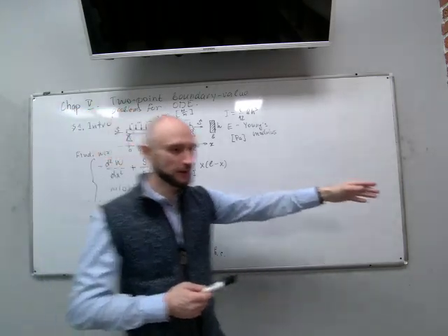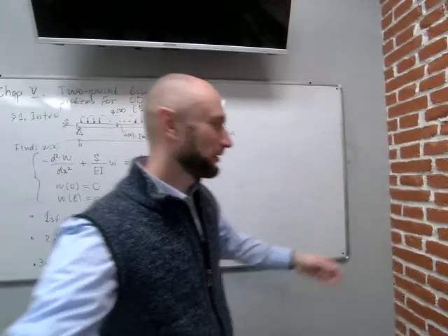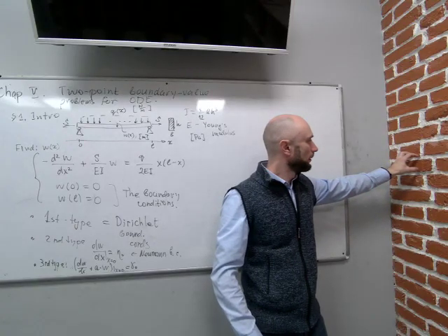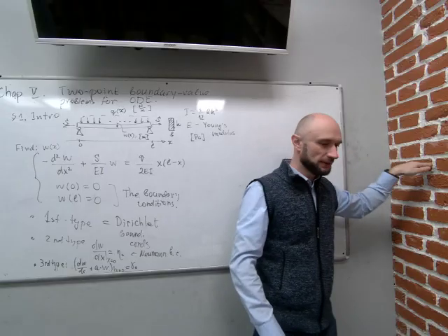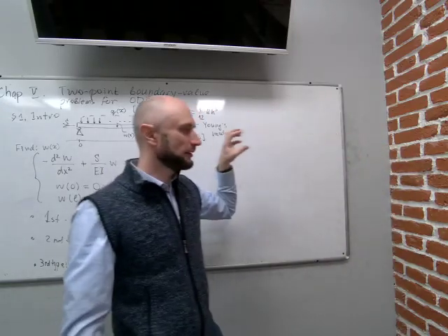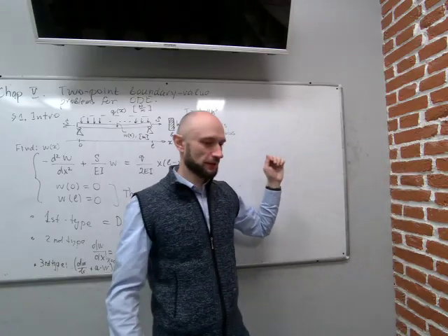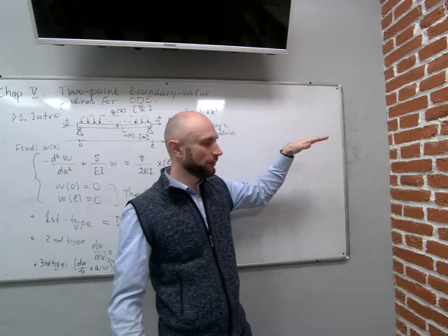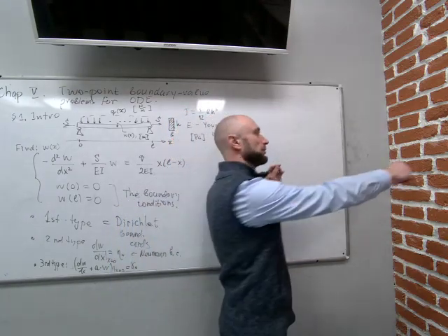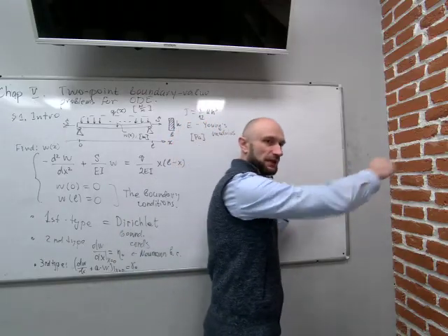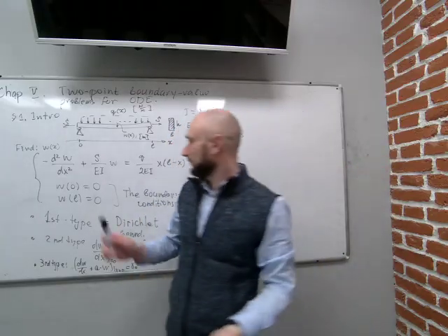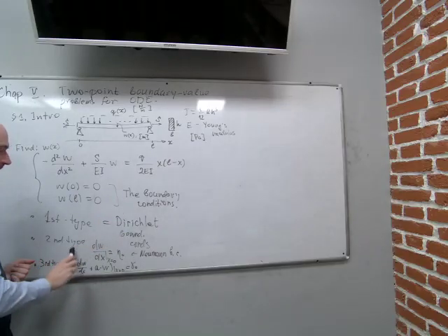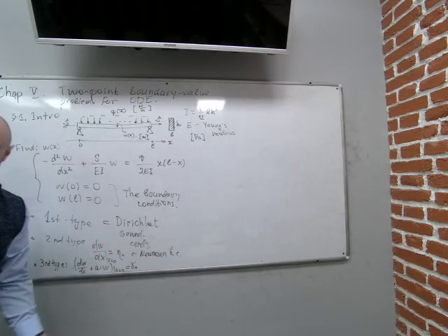You have a wall like this, like this brick wall, and you have a beam that's embedded into the wall, and it extends to the space here. So suppose it is only loaded with its own weight, and you will need to know its shape, how it will bend under its own weight. Then you will have the case when on the right hand side, on this free end, you will only have the second type, the zero second type boundary condition, minimum condition.